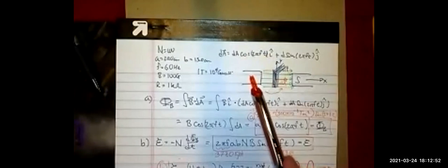Isn't it kind of interesting how easily you could make an electric generator yourself? Anytime you get something to rotate at a fairly uniform rate, you're going to get this current doing this. And in fact, if you did see how my loop has sort of one coil, if I did one coil and then did another at 120 degrees away, and then another at 120 degrees away, then notice I'm getting a 0 each time the dA vector lines up with the magnetic field. Well, that would be the case for each of those. So when this one's 120 degrees spun around that way, this other one comes in, it's reaching 0. And then when it spins another 120, then this other one comes around and it reaches 0. So you end up getting 3 currents like that, and they're each out of phase by 120 degrees. And turns out that's exactly how the electricity is brought into your house. It's called triphasic.